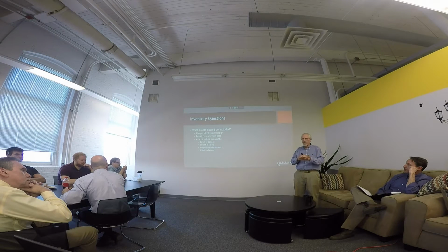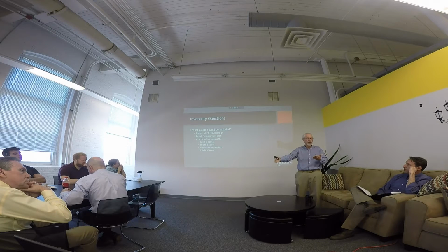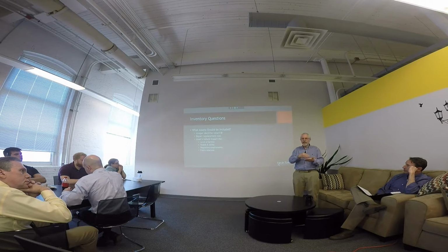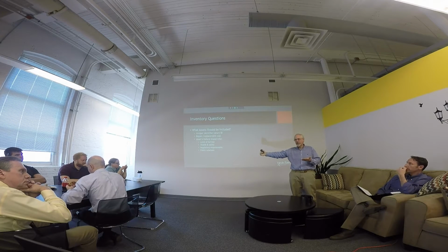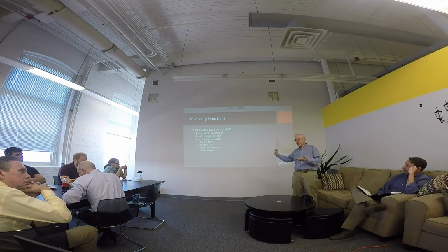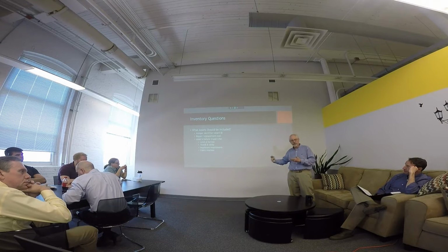So for manholes, for Hampton, every manhole number has a pump station identifier in it. So you look at a manhole and you know which pump station it goes to. If there was a spill of gasoline or anything like that, you'll know which pump station to shut off to prevent it from going further down the system.